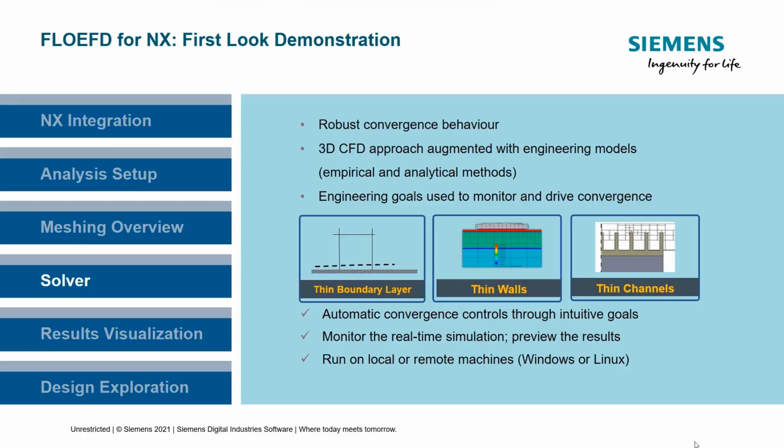The benefit to the user of the FloEFD solver is that there is automatic monitoring and convergence behavior using intuitive goals. The solution can be monitored in real time to ensure results are sensible and that there haven't been any errors setting the model up. The solver can be run on a remote machine to free up local resources.